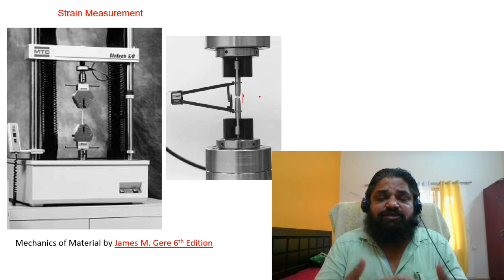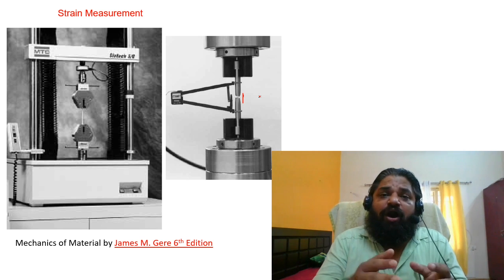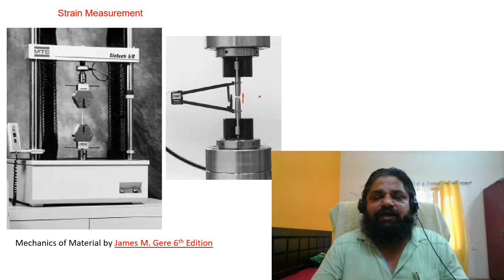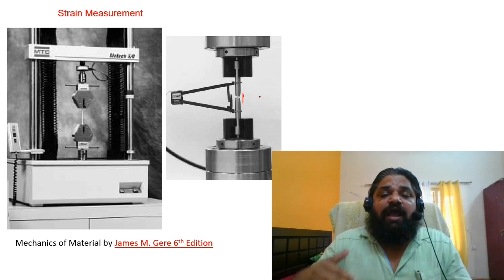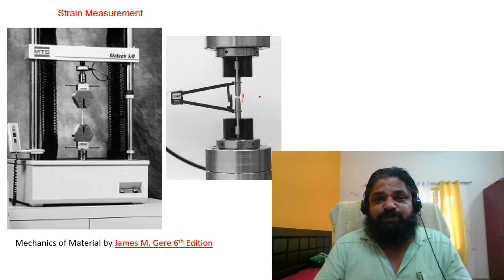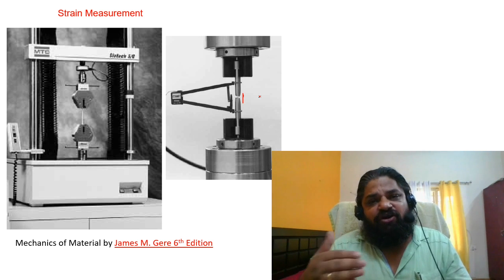Similarly, we can also calculate the shear stress or shear strain, that means the component which is parallel to the body. All these mathematical expressions are well known to us. During the discussion of principal stresses, we also calculated what the principal stress is, and why we call it a principal stress, and its components, that means maximum principal stress and minimum principal stress, and the corresponding normal stress and shear stress existing on an inclined plane.